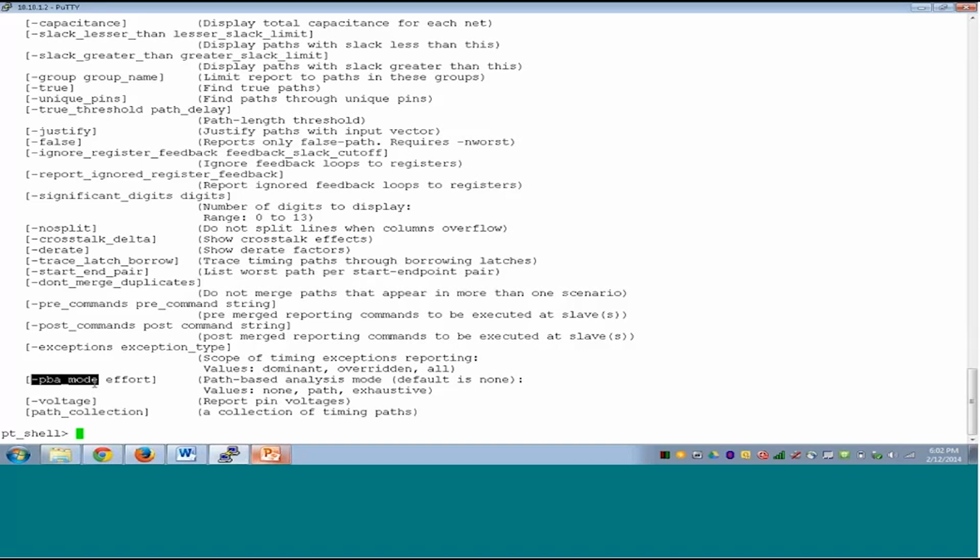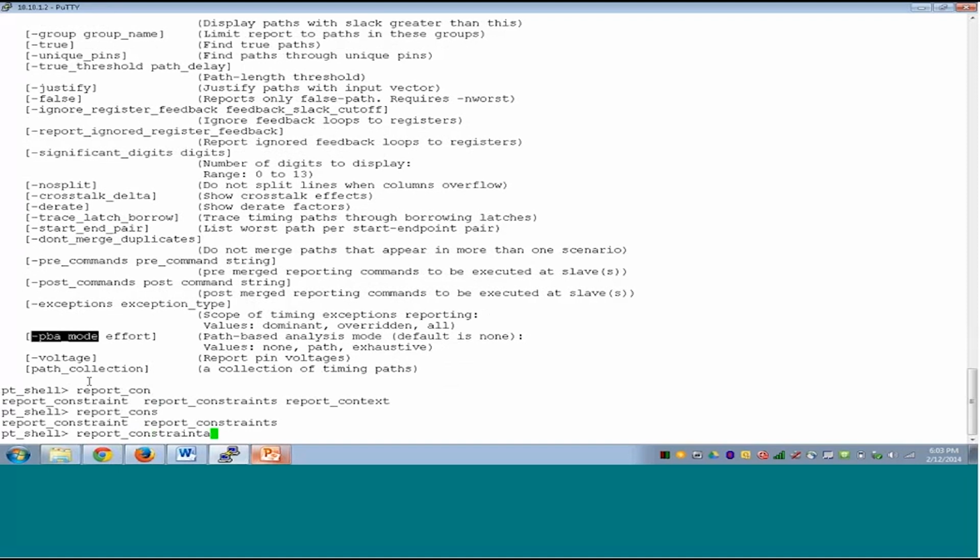We discussed the graph based analysis where the timing tool will maintain one slew number, which is for the worst slew, for cells which have multiple inputs. PrimeTime cannot keep the complete data. So what we could do, let's look at the worst violation first. Let's look at the report constraints minus all violators. Let's now analyze this design for violations.